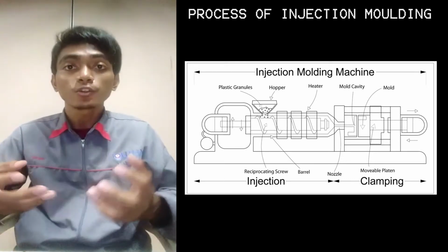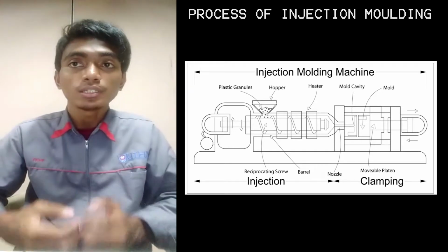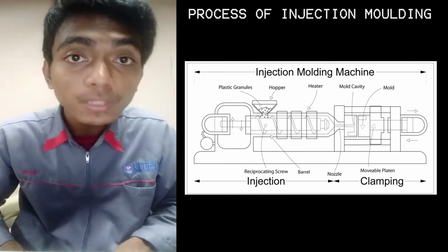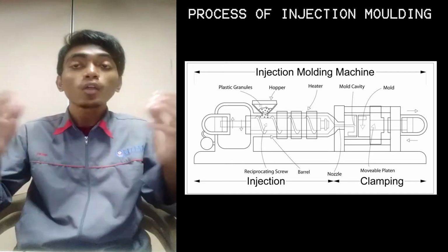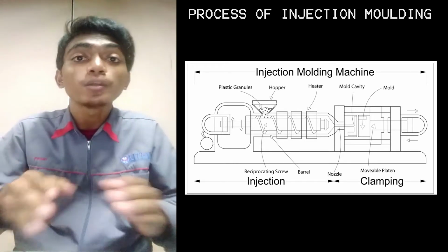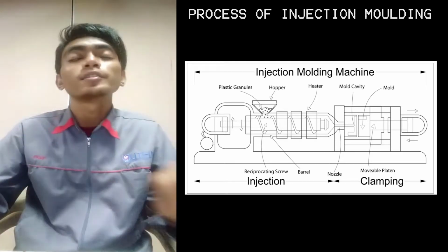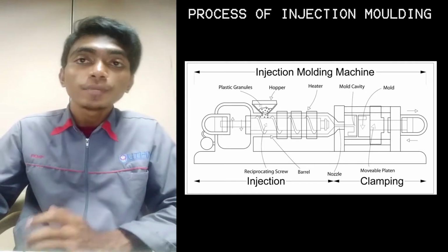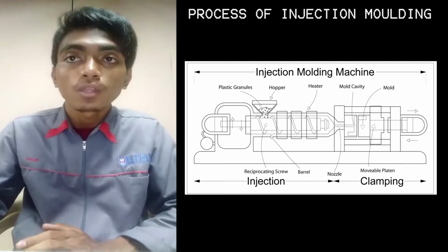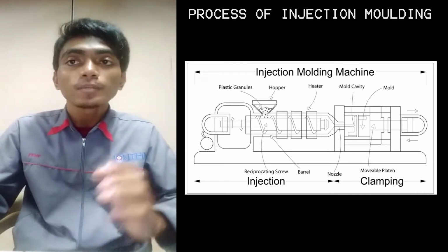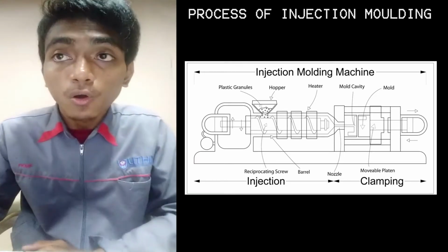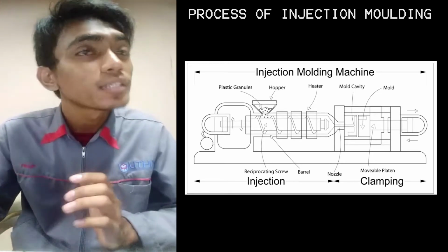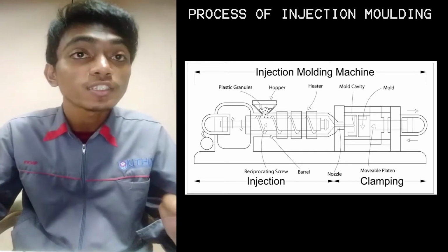The hopper is the large container into which the raw plastic is poured. The hopper has an open bottom which allows the material to feed into the barrel. The barrel contains the mechanism for heating and injecting the material into the mold. The mechanism is usually a ram injector or reciprocating screw. A ram injector forces the material forward through the heated section with a ram